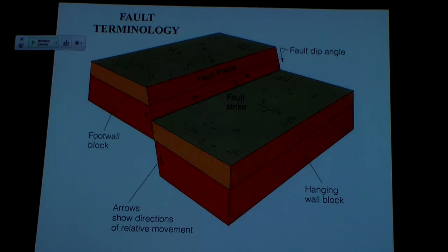So I just get my compass absolutely level with a little bubble level in the compass, put it up next to the rock, and whatever that compass bearing was, that's my strike. It tells me the long axis direction. And then I need to measure the angle that it's dipping into the ground. And again, I use a little inclinometer, and I measure that off of the horizontal plane. My instrument has a little level bubble in it to tell me where that plane is and what to measure.